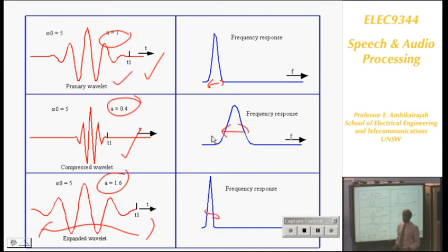So what you would have, if you are doing frequency analysis using wavelets, you create all these wavelets and store them in a bank as an array. Then depending on the analysis you want to do, you start with the lowest one, take that one, and then you compress it as you go to high frequency, and when you come to the last frequency, it will be well compressed. That means a very small, narrow window, right? That does not happen in the short-time Fourier transform. We have a fixed sine waveform of a fixed window length.